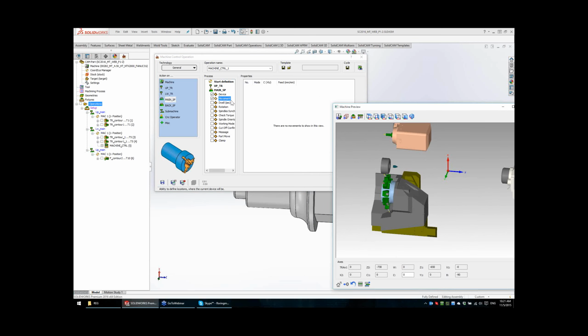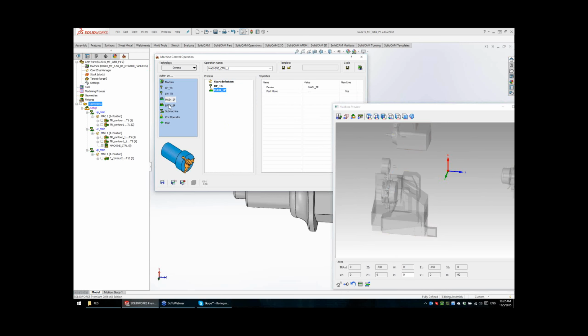So this option is not a correct one. So I'm going to do the part move. I will rotate the C-axis and the part will rotate together. We know from the setup that the part is connected for now, up to this stage, on the main spindle. Okay, so the main spindle with C-axis on 0.